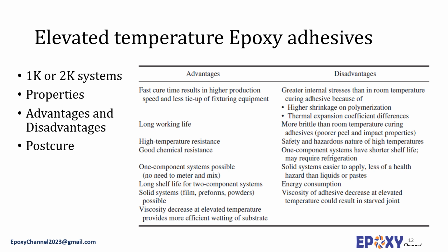Moreover, many epoxy adhesives are beta-stage resins, in which, during the cure, the resin experiences a semi-cured stage, in which the reaction between the epoxy binder and the curative agent has taken place but has not been completed. In this semi-cured stage, the adhesive is still fusible and soluble and to some extent flowable. However, upon applying further heat, the curing procedure is completed and the bond is formed and stiffened. Beta stage enables formulating resins for one-component adhesives, for example films, powders, and preforms. Therefore, it yields a better consistency amid the metering and mixing stages for the user and reduces the risk of wastage. Aromatic polyamines and solid forms of diglycidyl ether bisphenol A epoxy resins can be used to produce beta stage resins.